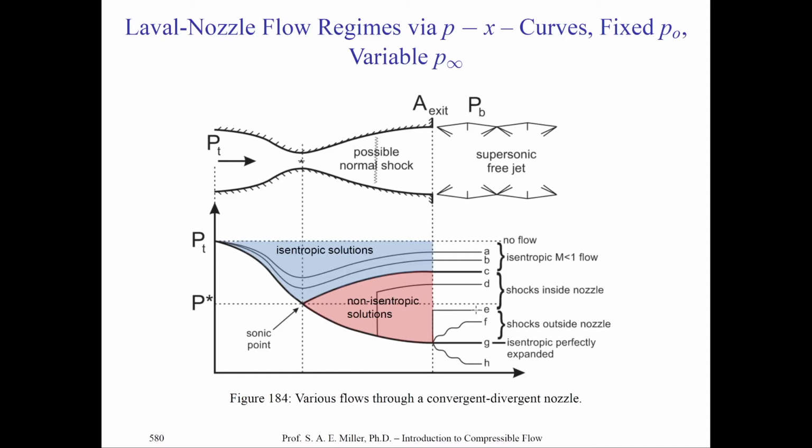And you can find that particular shock wave position also through the previous approach we just discussed in the previous classes. Now let's say we put the nozzle pressure ratio even a bit higher. Then what will happen? Either the flow will become supersonic through the nozzle, and indeed it will exhaust supersonically, but one of two things will happen. Either shock waves will form in the nozzle exhaust only and not in the nozzle itself, or expansion waves will form at the nozzle exit and not in the nozzle itself. These two cases are F and G, and we won't really be able to study them much until we understand the theory of expansions and shocks.